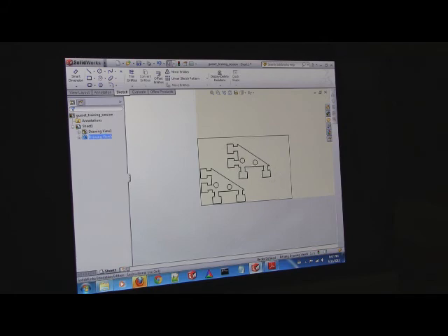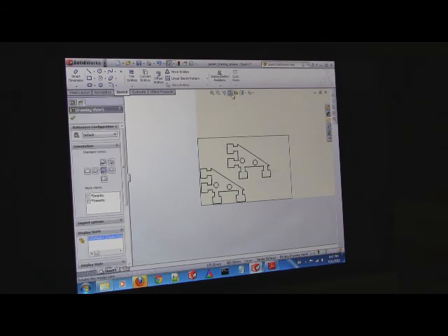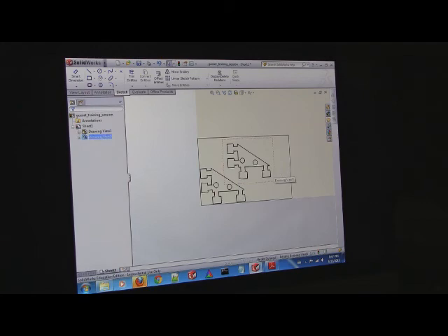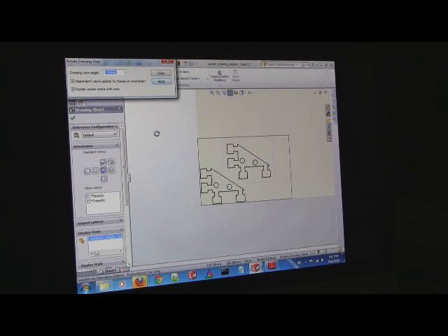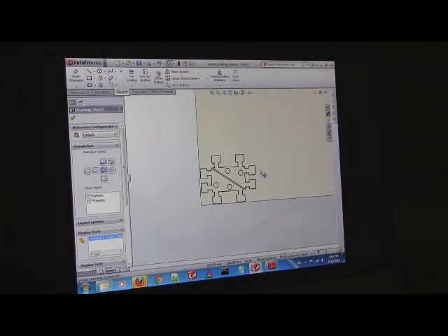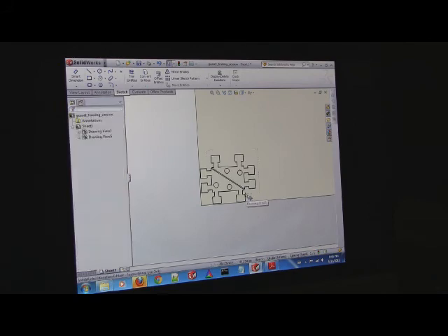Yeah. So what you do, and I've been doing this like 6 years and I only learned it last week, select this drawing view and see this button right here? Rotate. Select, I don't know, is that 180? 180. Apply. Booyah! And now we move it down and we go here. And now we're wasting basically no wood whatsoever.